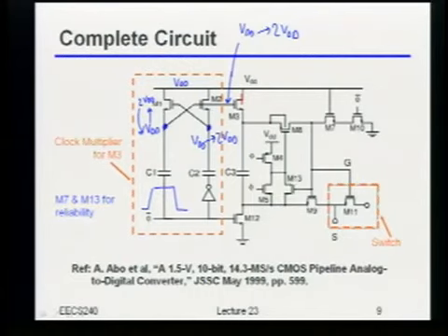By the way, these are very common. There are a lot of places, even in digital circuits, where occasionally you want voltages outside of the supply rail, and this is a very common way of doing it. So that's what this NMOS switch is doing. All of the stuff right here has to do with making sure you can actually connect this capacitor across the VGS of the input of the sampling switch without blowing anything up.